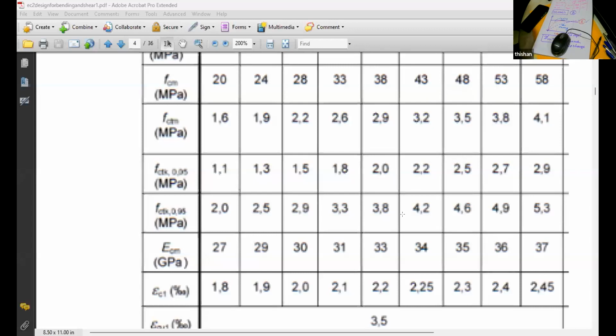Now suddenly you find you are even satisfying the 5-year return period on the wind-induced acceleration limits. And you'll find you have a much superior product. And that product improvement has come from the concrete technology that you have used, not by the design. Is that clear? Yes, sir.